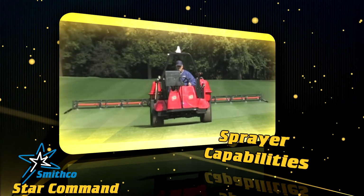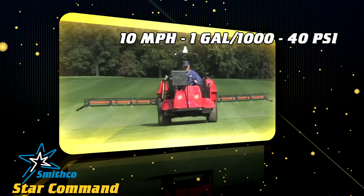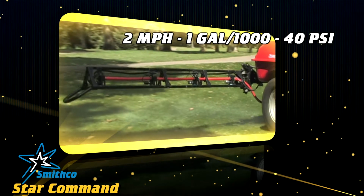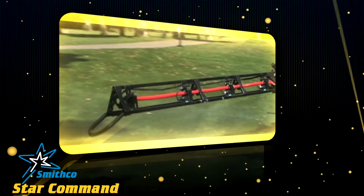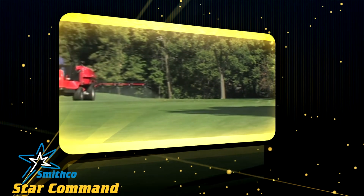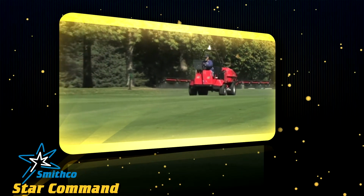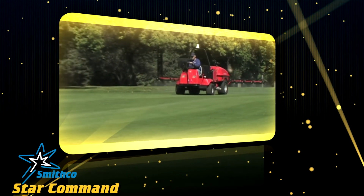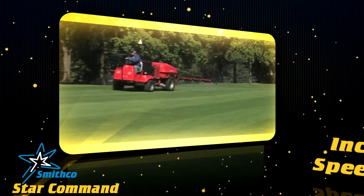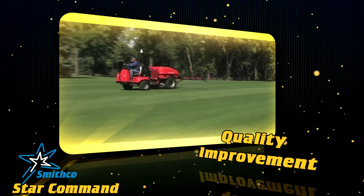Sharpshooter allows the operator the option of spraying to the maximum capability of the sprayer, typically 10 miles per hour, yet it also affords the operator the ability to slow down to 2 miles per hour when the application so demands. The amazing part of Sharpshooter's wider speed range capability is that it does so while maintaining a constant rate, a constant operator-set pressure, and a constant, consistent droplet size and pattern. In short, the operator has increased speed range capability with an actual quality improvement.